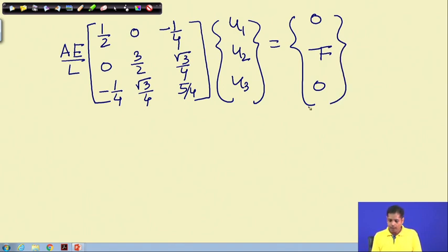Okay. Now, in this expression you check that this stiffness matrix is not singular. Now, why is it not singular? Because you have already given the constraint. This is the reduced stiffness matrix, after the partition, with the information from the global stiffness matrix; you applied the constraint and reduced the global stiffness matrix to this.